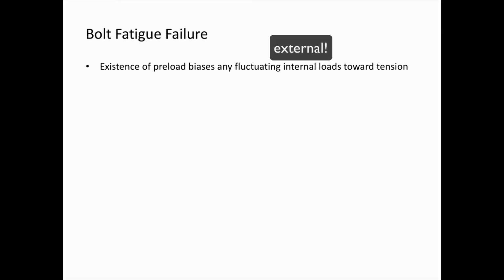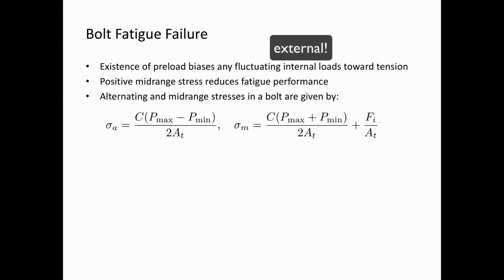Let's talk very briefly about bolted joint fatigue failure. The existence of preload biases any fluctuating internal loads toward tension. The preload on a bolt, that is a tensile force. If we have a positive mid-range stress, this reduces fatigue performance.